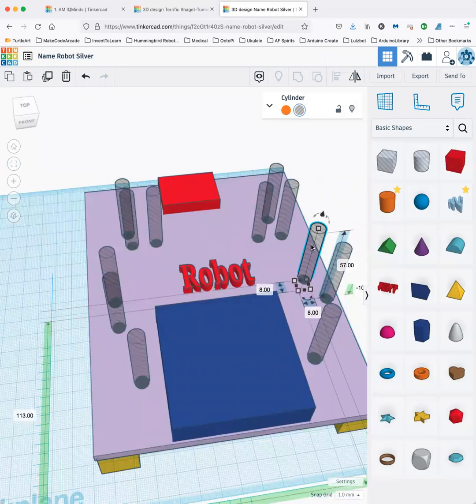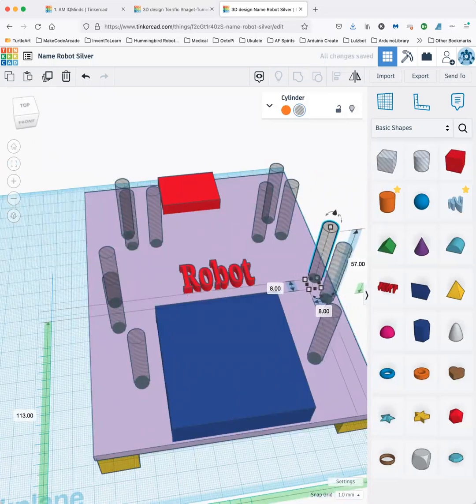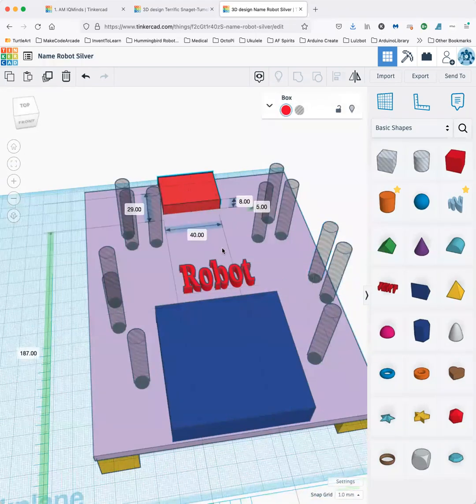I'm also having you put a second hole in, because I think what we'll do is, since the motor shield is on the bottom, we're going to put an LED on that switch circuit, and that way it'll remind you to turn them off. I don't have that on my prototype robot, and I've left my battery cases on overnight, and that's not a good idea.